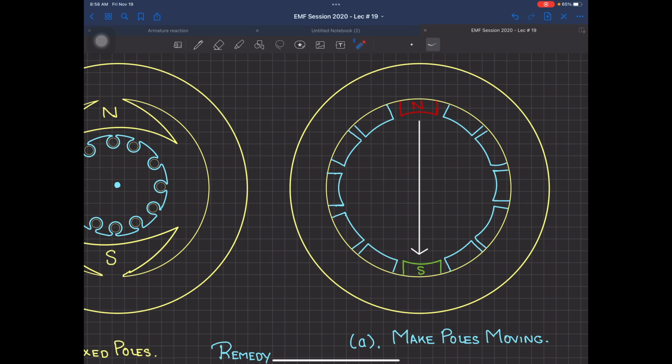But the problem here is that you are going to have how many poles over there? You have 1, 2, 3, 4, 5, 6, 7, 8, 9, 10, 11, 12. You have 12 windings and you have to energize those windings by some transistor or MOSFET. Now this technology was not existent when Faraday actually gave the idea of induction machine.